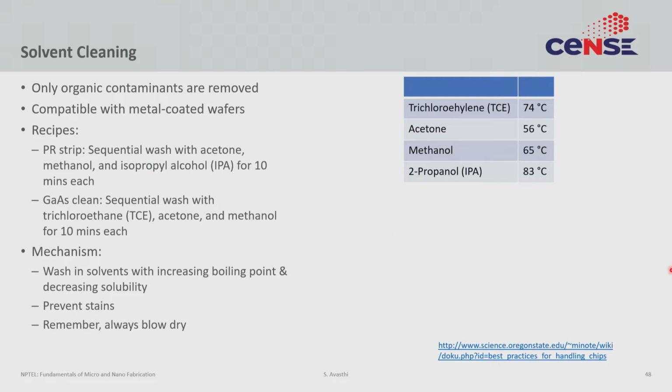The last wet cleaning technique I would like to discuss is solvent cleaning. So solvent cleaning is fairly simple. We are using only organic solvents, say acetone, IPA, etc., to dissolve away some organic contamination. Now that contamination can be from multiple sources as long as it is soluble in that organic material.